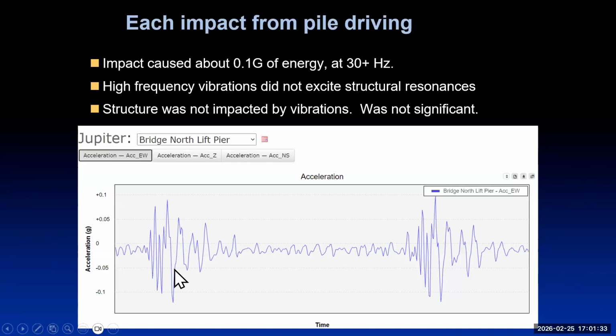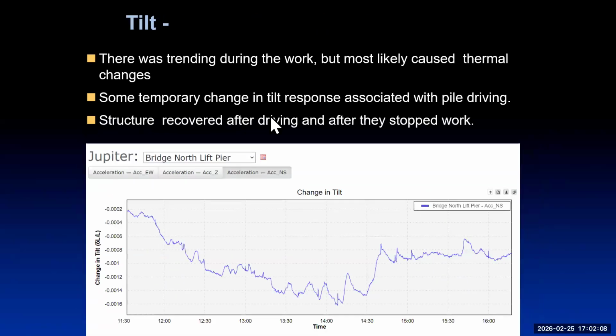But traditionally, the way they look at it, they pick one peak and they take one frequency off of it as if that were the only excitation and band of energy going into it. And that's simply not the case. You can see in this time history that you got a number of different frequencies. Then you have a decay, and then you have the second impulse, and it's different than the first. So you really have a little more of a chaotic system than would otherwise be understood. So it's actually quite interesting when you get into it.